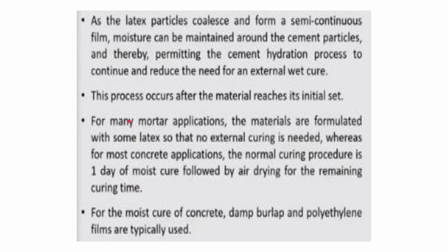In case of many mortar applications, the materials are formulated with some latex so that no external curing is basically needed. And in case of most concrete applications, the normal curing procedure is basically 1 day of moist cure, followed by air drying for the remaining curing time. That is for the normal concrete casting.